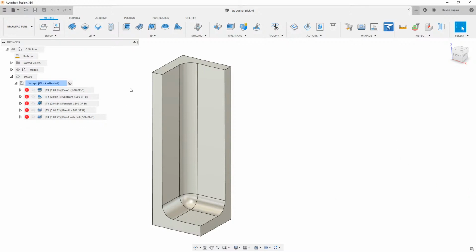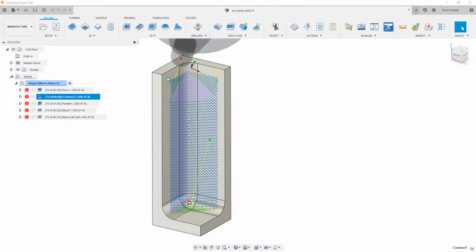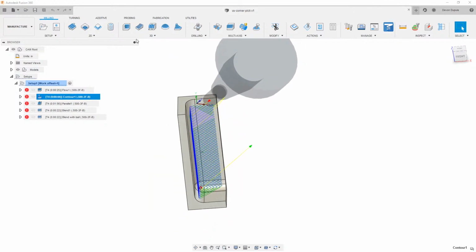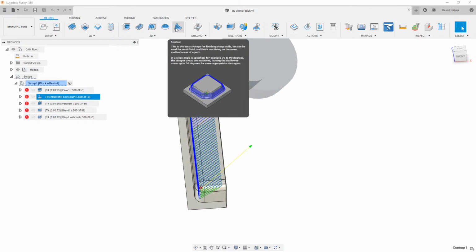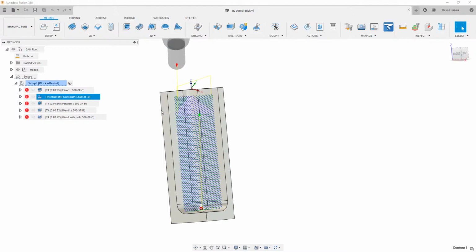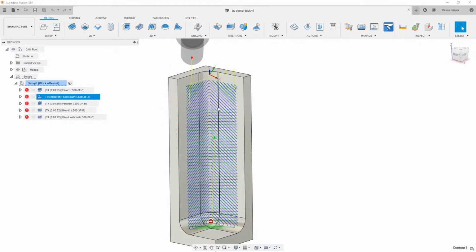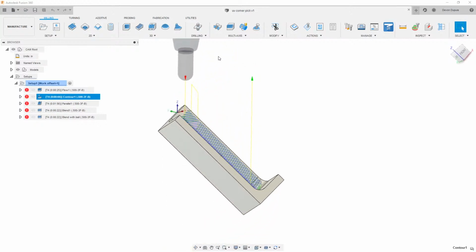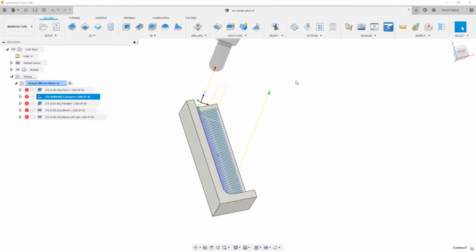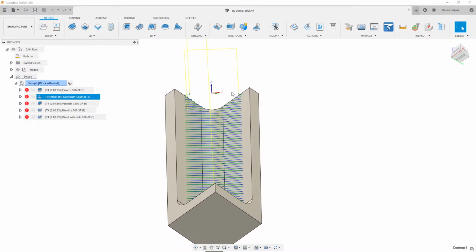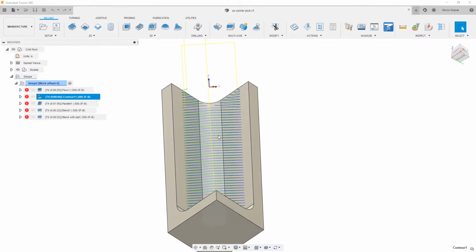So what do people try to do to fix this? Maintaining the tool orientation that we have, they might try a contour toolpath, like a constant Z level. This gives us okay results, but not really what I want. It looks kind of weird here, almost like a fingerprint, but it is doing its job. From our tool axis normal, it's doing a really good job of slicing the model and laying a toolpath wherever there needs to be contact.